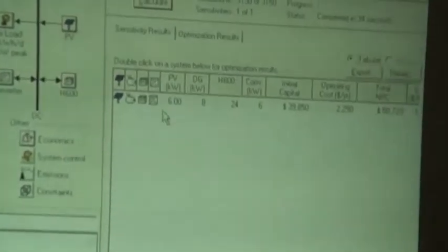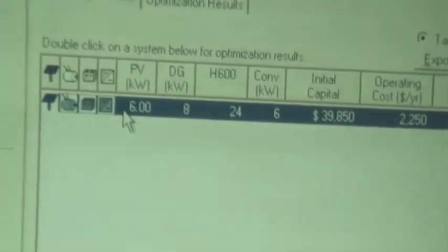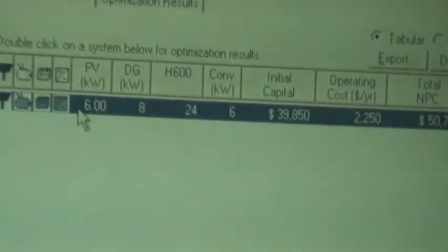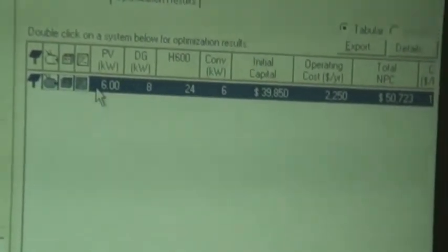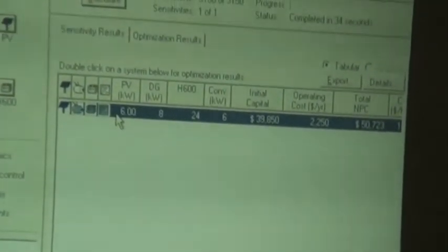I ask because it's one battery string really is what we have here, right? In practical terms, what we've seen with other ones is that if one cell fails, the whole string goes down, and now your site's down. So I wonder about the redundancy. Yeah, a lot of times we'll do two strings, because if one fails, you've got that backup. Yeah, I think this is a very valid point. It's all about strategy: do you want to strategically create two sets of 400 ampere hour batteries, or do you want two sets because you want to get a higher autonomy? These are the strategies that you have to set. So we will go into that.